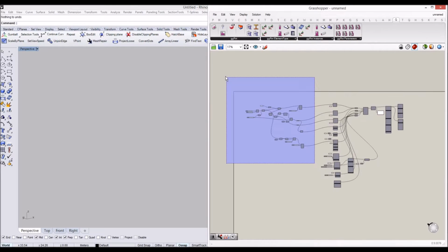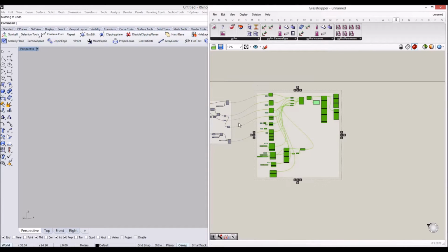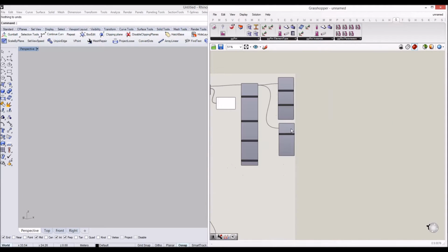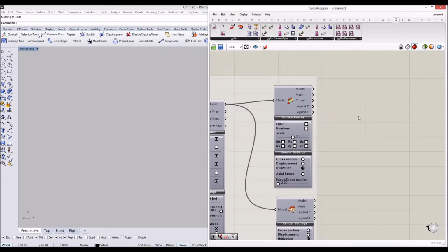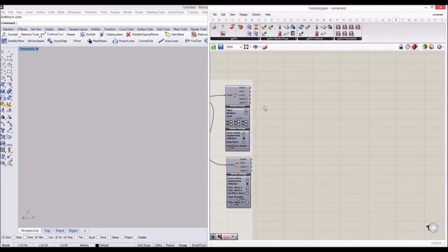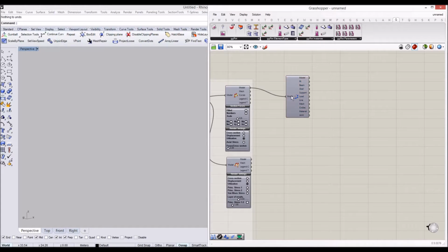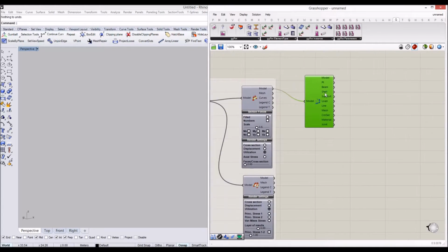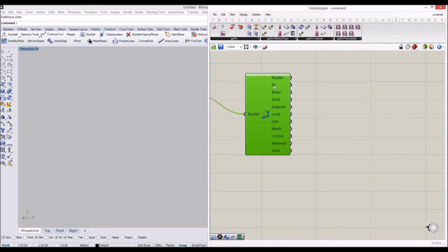So I would like to disassemble our actual Karamba model so that we can easily use those disassembled model component geometries to send to Revit. So I'll just type Disassemble Model component in Karamba, which allows you to disassemble our calculated model into every component, like model, points, beams, shells, and etc.